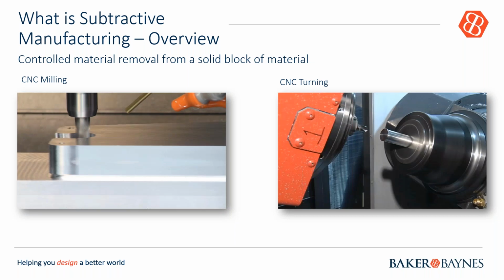Let's see some of the basics of the subtractive strategies again. If we look at some of the strategies that are available to you, we find that there's 2D, 2.5D, and 3D machining. You've got fourth axis tool orientation that you could work with, fourth axis simultaneously, which moves in both directions, as well as the fifth axis tool orientation. You've also got 3+2, and there's also fifth axis simultaneously. So let's have a look at this. As you can see, pretty straightforward.